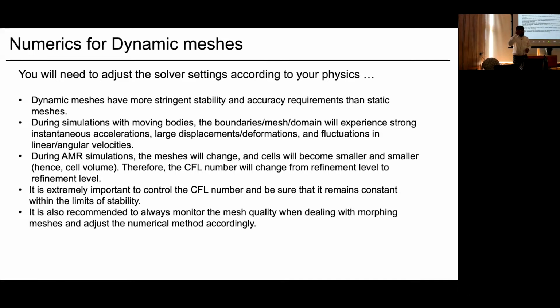It's also recommended to always monitor the mesh quality. OpenFOAM has the capability that when we run a mesh morphing simulation, at every time step it shows you the mesh parameters, and whether at that particular time step your mesh parameters are okay, or going beyond the threshold limits that you have set. Accordingly, you have to take a decision whether you want to continue the simulation, or stop the simulation and remesh the problem with the previous solution. So this remeshing can be opted for in mesh morphing problems by monitoring the mesh quality at every time step of the simulation.